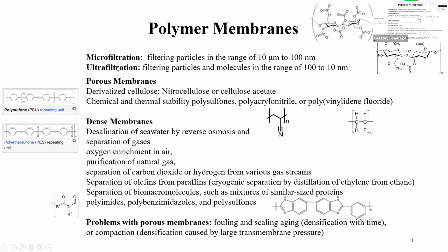So large scale things, and then the pores. In this range, you're starting to get into what they call Knudsen transport. That's when, if you're looking at the kinetic theory of gases, the gases have a mean free path. And if you get a pore smaller than the mean free path, the transport's not governed by gas molecules hitting each other, where you get Brownian motion and diffusion. It's guided by the gas molecules hitting the walls of the pore.